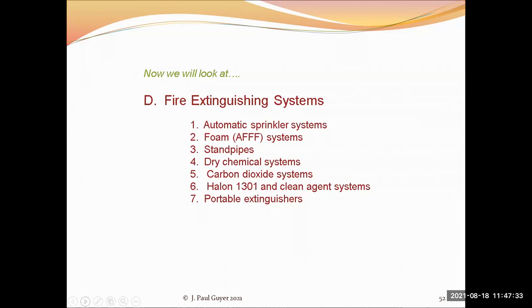It would reduce the oxygen level to a point where the fire could not burn, but there was still enough oxygen remaining in the space that it would allow the people enough time to get out of the space, and it would not damage the electronic equipment. This Halon 1301 product was, as time went on, identified as an environmental hazard and has been pretty much banned and taken off the market now, but it's been replaced by some comparable gas systems that are lumped together and called clean agent systems.